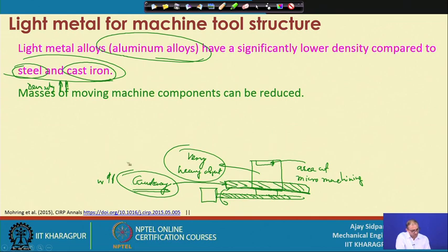So, when you are moving this by lead screw, the motor will be loaded more, because it has to provide such a high torque so that it can move this object in different directions, maybe to and fro or left or right depending on your axis. So, you cannot get a very fast movement, that means your feed rate will be very low.